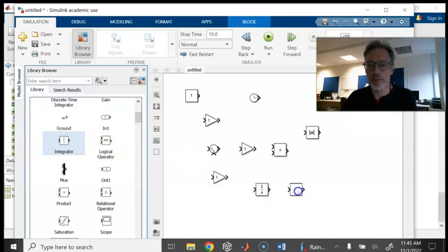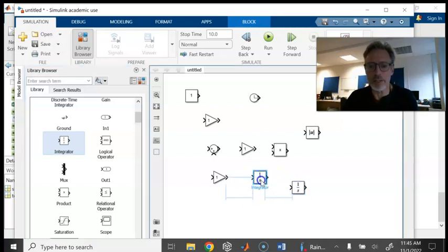The integrator blocks have a 1 over S in them. If you've done a controls course and you're familiar with Bode plots in the S domain, you'll recognize 1 over S as a Laplace domain integration. So it doesn't have the nice little curly integral symbol you may be used to. And that's okay. Now, let us begin. This is one of those things where when you see this done the first time, it may click and you'll say, oh, that's really neat.